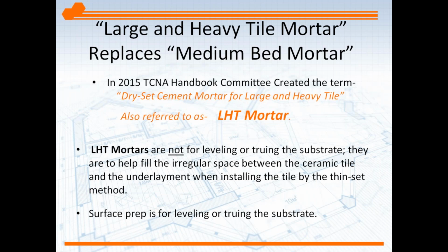Medium bed mortar had referred to a different type of bonding mortar, the mortar that you use to bond the tile to the substrate. It was a bonding mortar that was able to go in deeper, which is required for large format tile, and I'll talk about that in a second. But that medium bed mortar term was confusing, so they changed it. They changed it to dry set mortar for large and heavy tile, which is referred to commonly in the industry as an LHT mortar. So summing all this up, when you have a large format tile, 15 inches or larger, you want to call for an LHT mortar, large and heavy tile mortar.